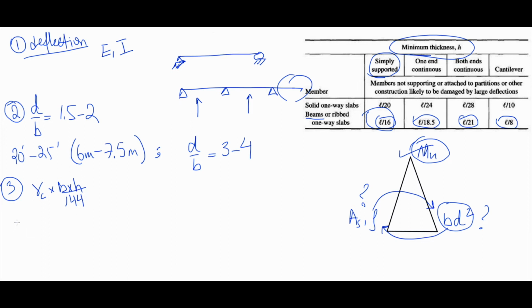After that, we have to calculate number 4, the load, because we got the own weight, we know what the loads are. Then you calculate what the moment is. Moment would be, for a simply supported beam, wL square over 8, for example. w is the load, the ultimate load, but you have to factorize the load. Finally, or not finally, we still have more steps.